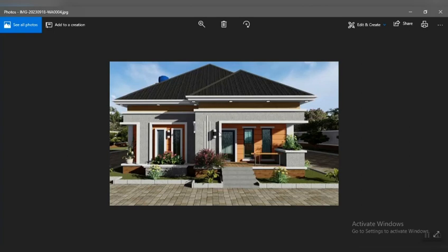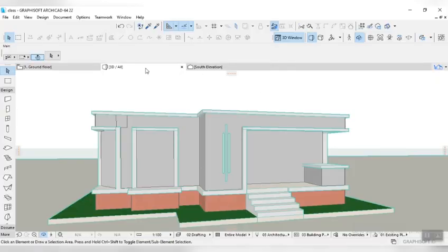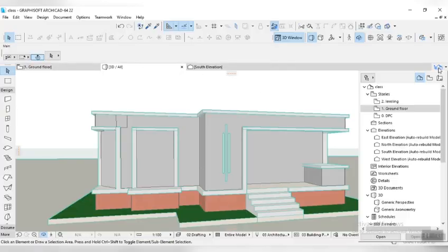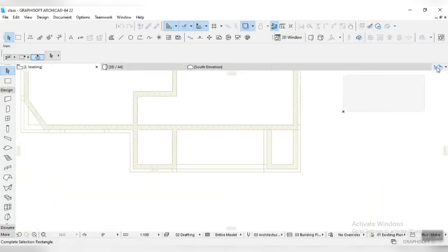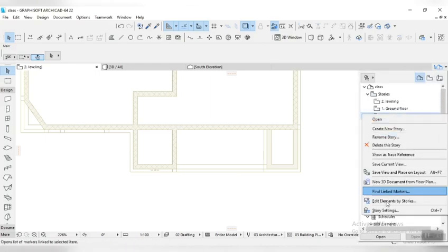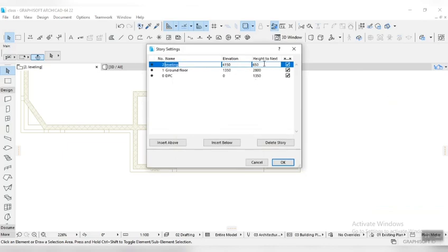The next thing, let's go for this upper leveling. So go back to your floor. You come to your story setting. Remember, we have settings for leveling. So let's pick it. First of all, let's check what we have for this leveling. Let's right click your story. Okay, we have 6255. Let's change this to 550. I prefer 550. Okay, let's change that.